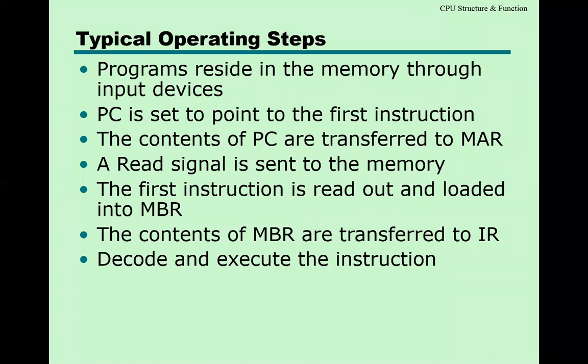Now it is transferred into the MBR, and then the instruction will be transferred from MBR to the IR, instruction register. So MAR, MBR, we have not taken an example, but the role is the same. PC sends the instruction address to the MAR, the instruction is loaded into the MBR, and after MBR, the instruction is loaded into the IR.